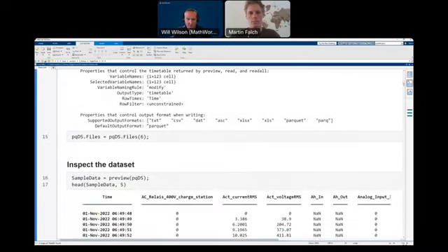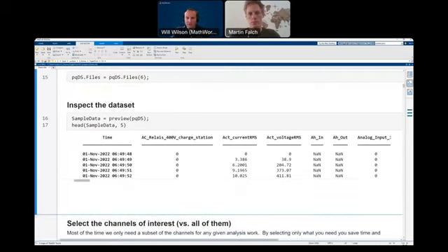Okay. Now for this example today, we're going to focus on the 6th file, which happens to be the month of November. Because there's no reason for me to run through all the data at once, I just want to illustrate the main idea here. When we preview the data, what we get back is a MATLAB timetable, where the first column is time, and each of the columns represents an individual sensor. Because this is a battery pack, we've got signals or channels like voltage and current and that sort of thing. There are on the order of 120 different channels for this data set.